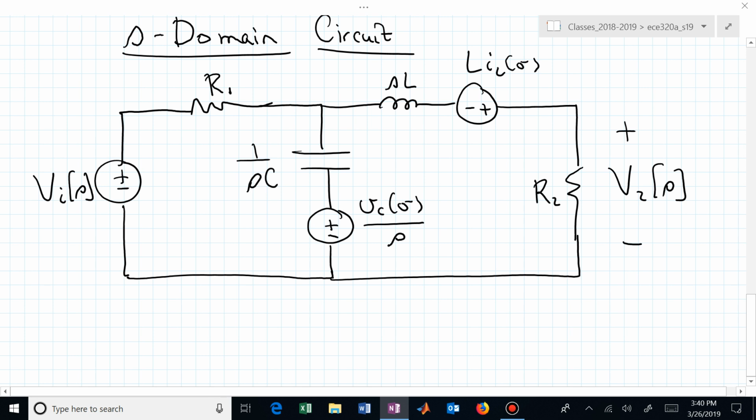Yes, that's true, but we will learn how to either incorporate these initial conditions as series voltage sources or as parallel current sources, depending on what kind of an analysis you want to perform. Here I'm saying, oh, we like mesh analysis, so let's not disrupt the two meshes that we had to begin with. And if we want mesh analysis, then we're going to incorporate voltage sources.